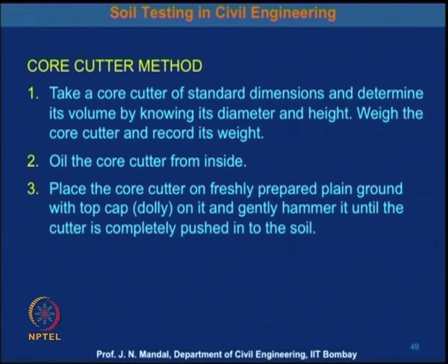Secondly, oil the core cutter from inside, and thirdly, place the core cutter on the freshly prepared plain ground with the top cap dolly on it and gently hammer it until the cutter is completely pushed into the soil.